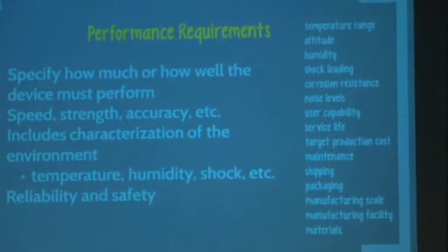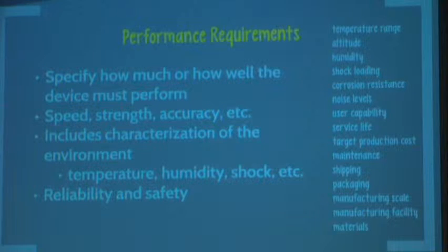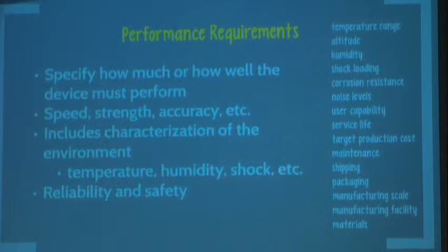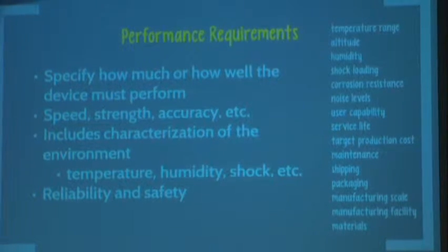That right-hand list is not exhaustive, but it will give you a good brainstorm when you go in to do your specs. Say, did I think about the environment, right? I'm designing a piece of electronic hardware that's going to be used in Africa, and the humidity is 90% all the time. Did I design it to be used in that environment or in the lab over here? Things like that you want to consider. You want to consider the real-world system where it will be used. Does that make sense to everybody? So those are the main spec types.